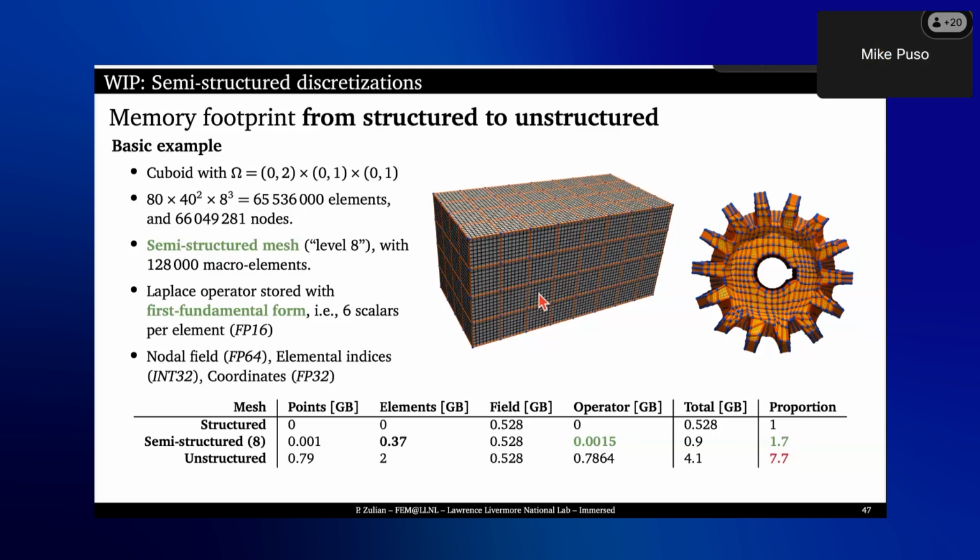Thanks. So I want to follow up on this. This substructuring looks very similar to a high order element. Yeah, the idea comes from there. But with high order, you have everything communicating with each other. If you have a deformed hex, maybe you use only one Jacobian. Anyway, have you compared the performance between the substructuring and a high order that would match the same number of degrees of freedom? No, I have not, but all this multigrid stuff I've done in the last two months. I expect on the CPU to still be more efficient with the low order version. On GPU, I guess probably not, but I'm not sure actually.